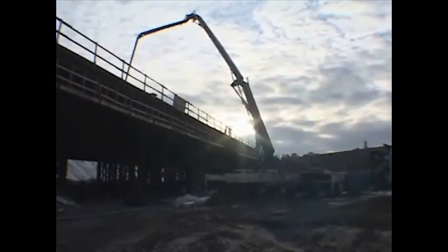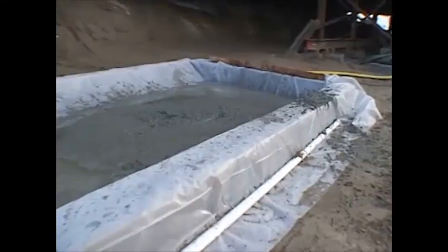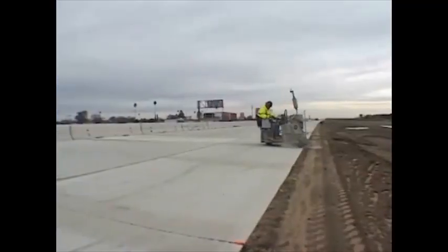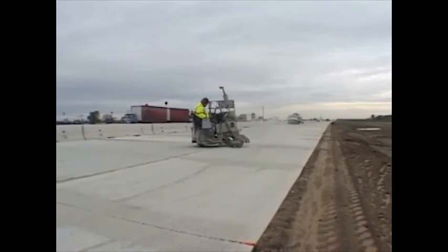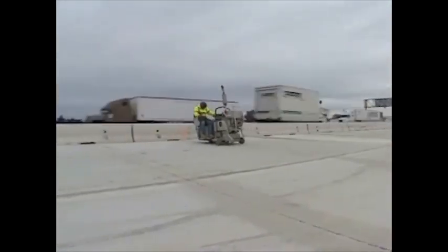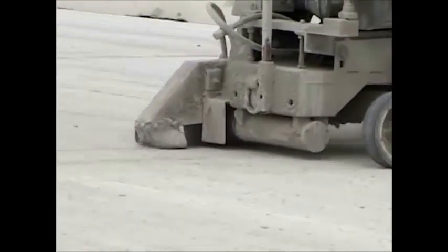The contractor's water pollution control manager must monitor on-site concrete waste storage and disposal procedures on a weekly basis, or as directed by the resident engineer. The water pollution control manager will monitor concrete working tasks such as saw cutting, coring, grinding, and grooving daily to ensure proper methods are employed, or as directed by the resident engineer.